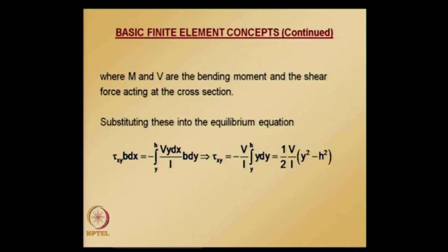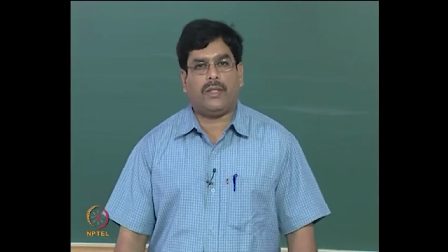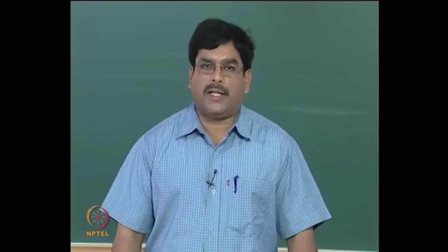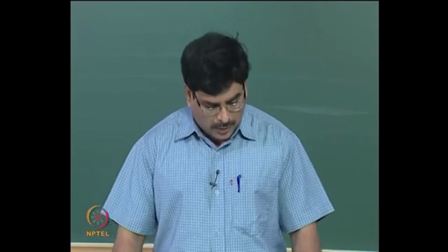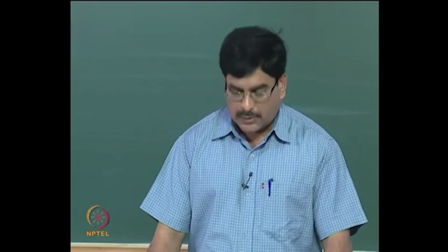So, we learned how to calculate normal stress and how to calculate shear stress. Normal stress is dependent on bending moment at any point along the length of the beam, and shear stress is dependent on shear force at any point along the length of the beam. So, once we calculate bending moment and shear force using finite elements, we can calculate normal stress and shear stress using these expressions.